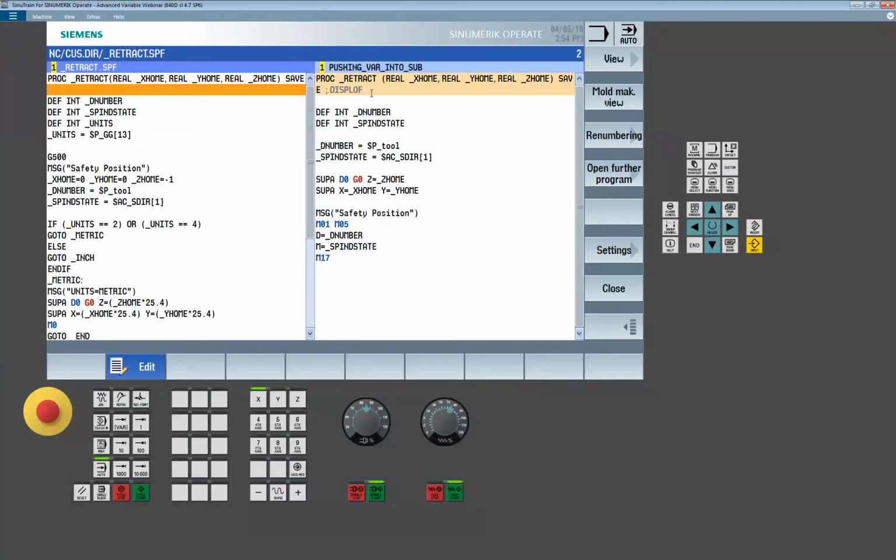I got the save. I'm not going to worry about the display off. There's a semicolon in front of it anyway. That's a good way to suppress these commands at the end. If you have display on or have the single block suppression here, if you're debugging, you may not want it there. So just put a semicolon in front of it. That's why I always have save first, because that's one I would never want to suppress. And then I'll have the rest of them.